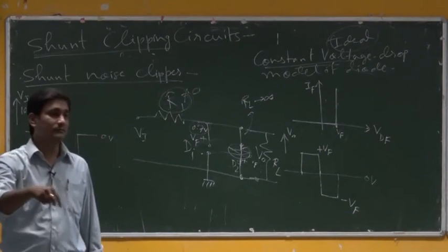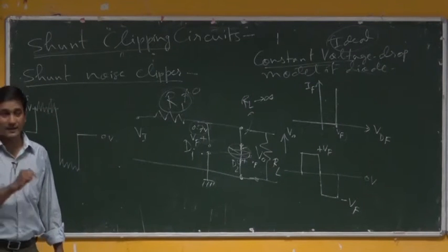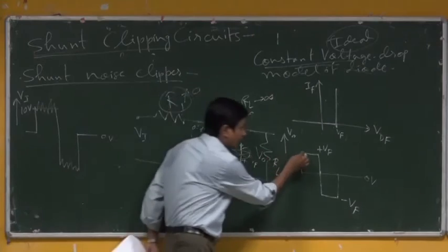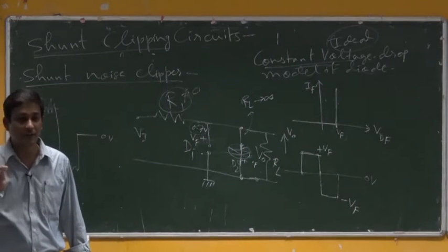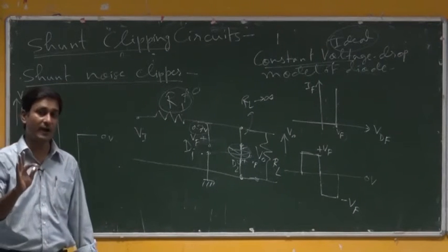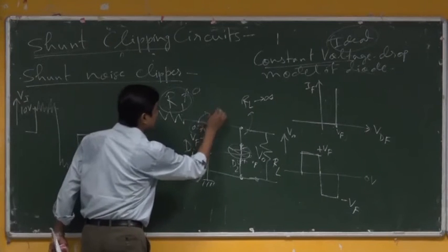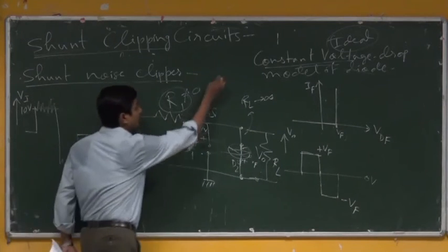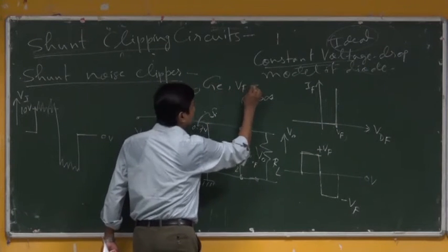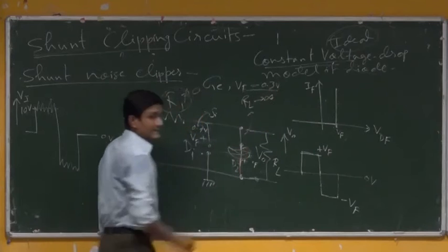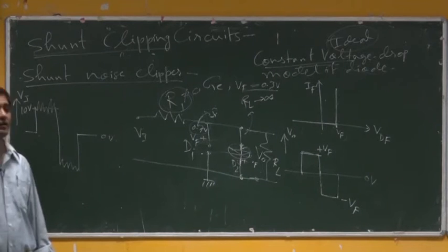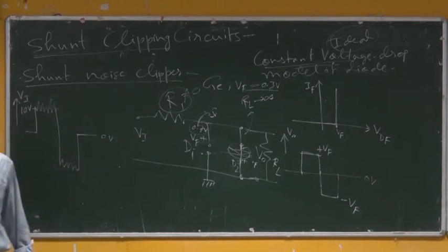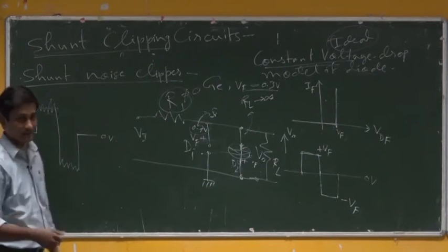Okay. Now, let us come to his question, what he has asked about, if it is not VF, but at a certain voltage level, I want the flatness, not at VF, because if one diode is given there, VF is defined for it. Just like for a silicon diode, the VF will be 0.7, or for a germanium diode, the VF will be say 0.3 volt in general. But we are not satisfied with that, but with a particular voltage we want this clipping action. So let's put one biasing to that circuitry. We will discuss rigorously on that circuit. Please come.